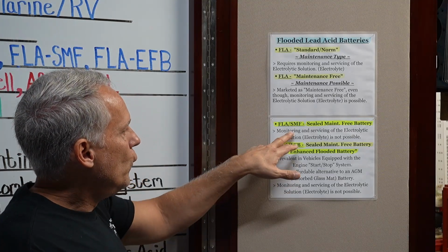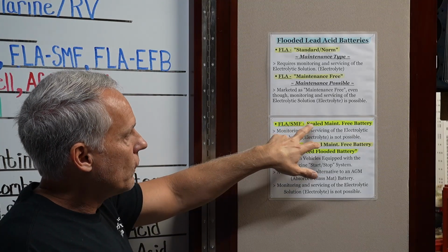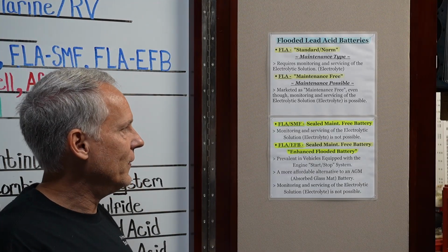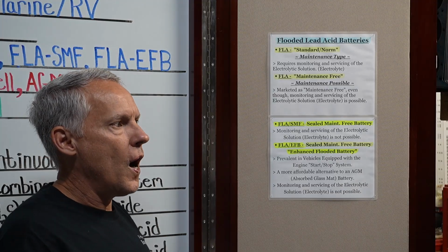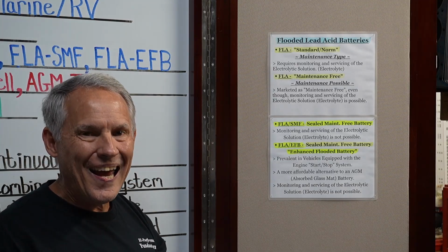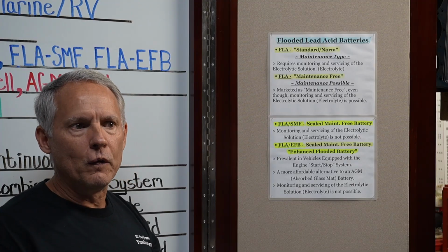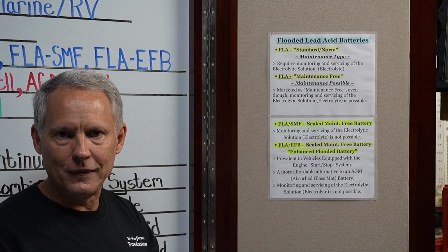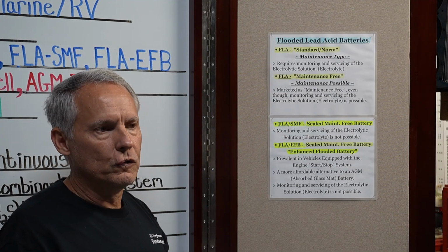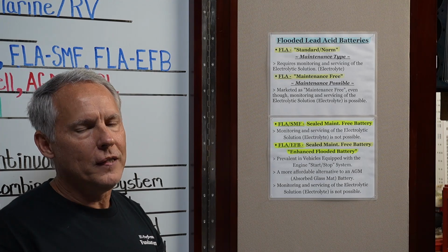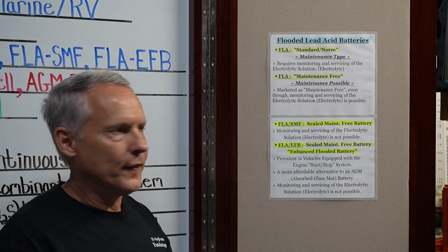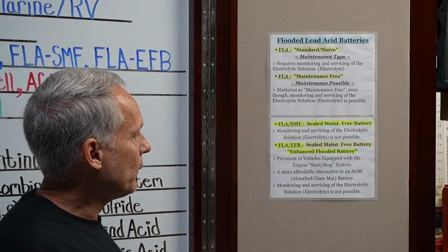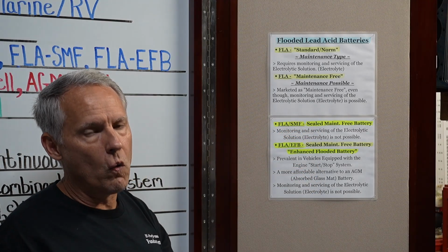All right, so from there, you get into your flooded lead acid sealed maintenance free battery. Like we had said, that's not an SLA battery with a VRLA system. It's not that. It is literally just sealed. They don't want you going in there. It makes it difficult. In a lot of cases you can, but if you do anything to the battery, like you cut the stickers on the top of it, you maybe cut away some glue to get the caps off, your warranty is void. So yeah, it may not be permanently sealed, and yeah, you probably can get in there, but I don't know if I recommend it or not. So that's an SMF, sealed maintenance-free battery. Monitoring and servicing of the electrolytic solution or electrolyte is not possible for all intents and purposes.